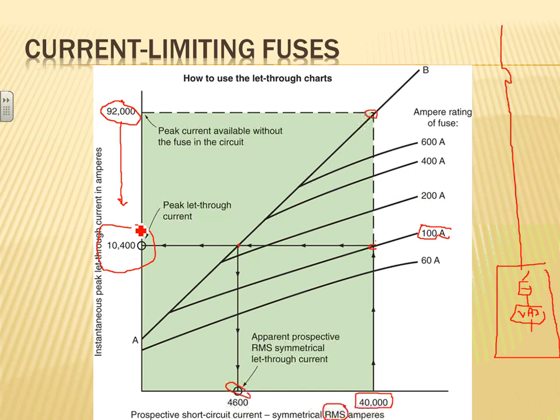That's where those guys always... The lesson I learned from Mr. Brumlich in Phoenix is that some of those fuse families have that curve published for a 40,000 amp max, and they have another curve for 30,000, another one for 20,000, another one for 10,000.